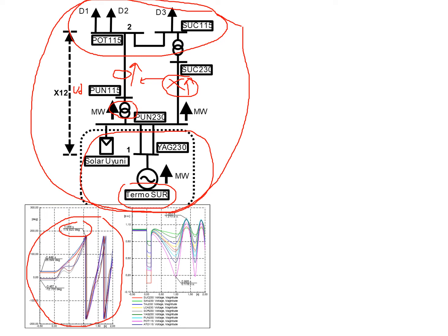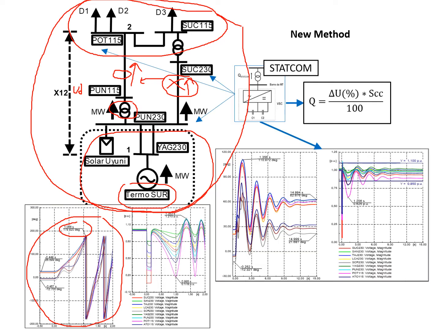help to show how the new proposed methodology determines the lowest capacity of the STATCOM and the best location of the STATCOM in this area. For this reason, the methodology in the first stage computes the sensitivity analysis and the participation factor in each substation and determines the highest one. In the substations with high sensitivity, we can install the STATCOM.